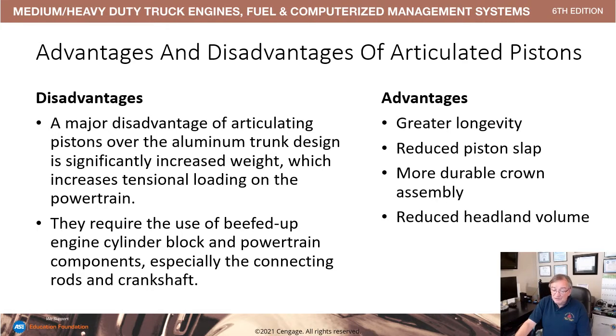For advantages, we have greater longevity, reduced piston slap because of the geometry, and a more durable crown assembly. Now that's a combination of heat transfer, lubrication, and reduced headland volume. The less headland volume we have, the more potential we have for a higher cylinder pressure.